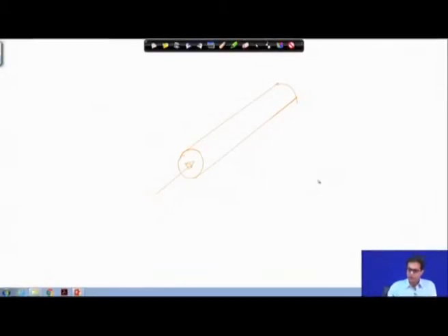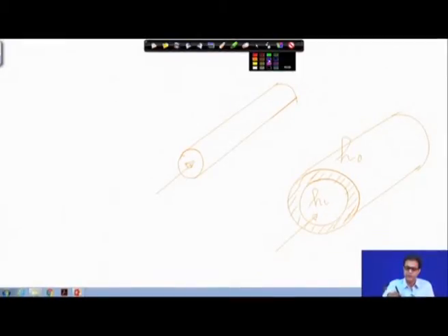So, when we talk about the internal heat transfer coefficient, and also this is the wall. Most of the time we neglect the resistance offered by the metal of this wall, and we also have the external heat transfer coefficient. So far in our analysis, we have assumed that this heat transfer coefficient has already been given to us, but this time we are trying to find out how these heat transfer coefficients are known or how these are to be estimated.